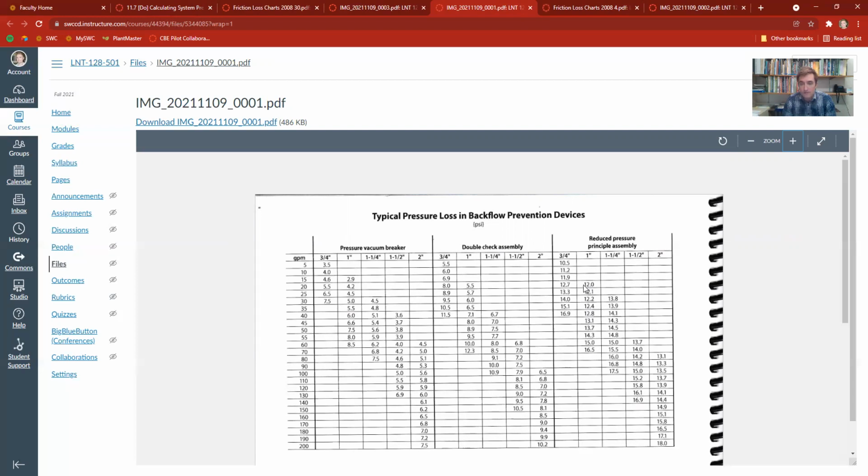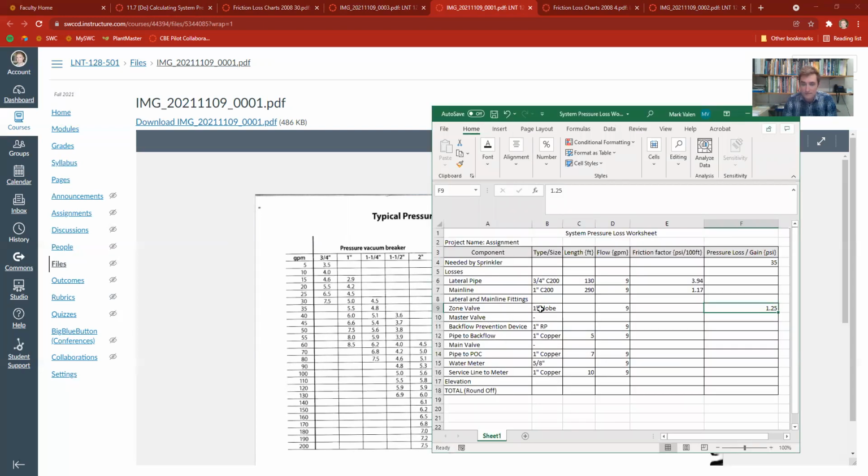We're going to just assume 12. It doesn't go down to our PSI range. At the size down, it's a little less than 12. We're going to say 12 just to be on the safe side. And again, the fact that it's not listed on the pressure loss chart is an indicator that it may be a problem with the selection.